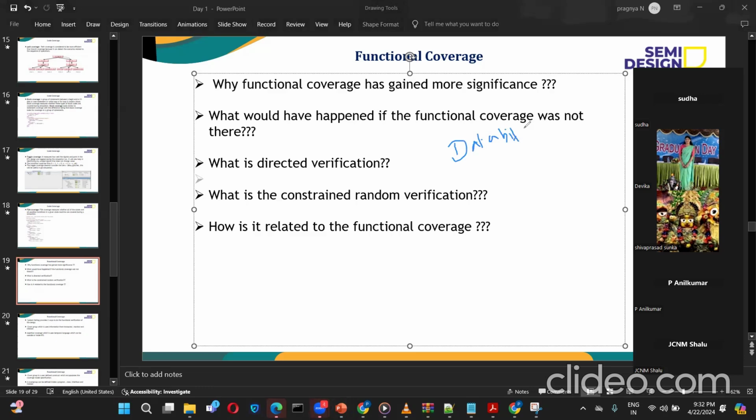In that case, I will not write one test case to test the data bits as 5 and another test case to check the data bits as 10. Instead, I will create a random variable for data bits in my base test or in a global config, and then I will randomize it. Each time it runs, it will have a new seed value, which means every time it will generate different data bits.